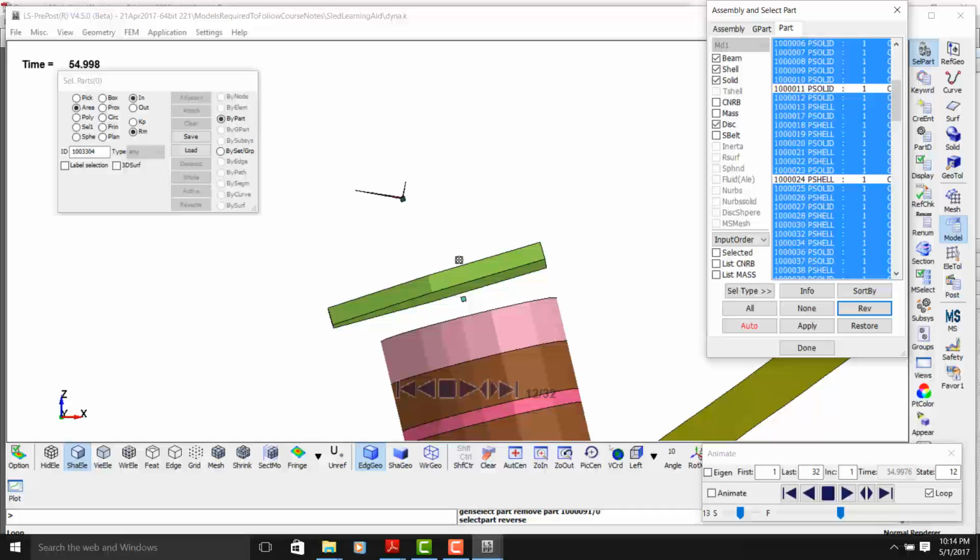We also find out the upper neck shear force, Fx, multiplied by 17.78, this lever arm. So you can see the question of a moment coming in. Whatever that is, you subtract it from the neck moment that the load cell is giving. There is a way to do it, and I think I've defined that in my dummy user manual. I've told you how to do that. You can go through it.